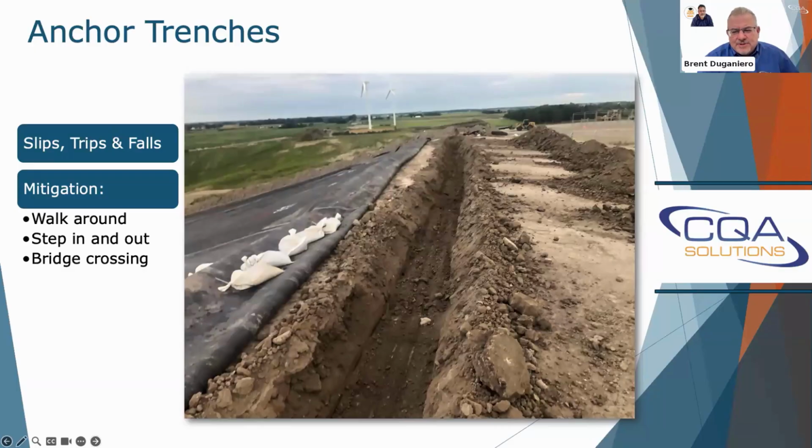So one option, which we do not recommend, is either jumping or stepping across that trench. So we need some alternatives. One is you could walk to the end of that trench and go around it, thus eliminating that hazard. But in doing so, you could actually find yourself in the line of fire of another hazard. Maybe there's an excavator over there excavating that trench. So you want to be careful that you don't find yourself walking into some other danger.